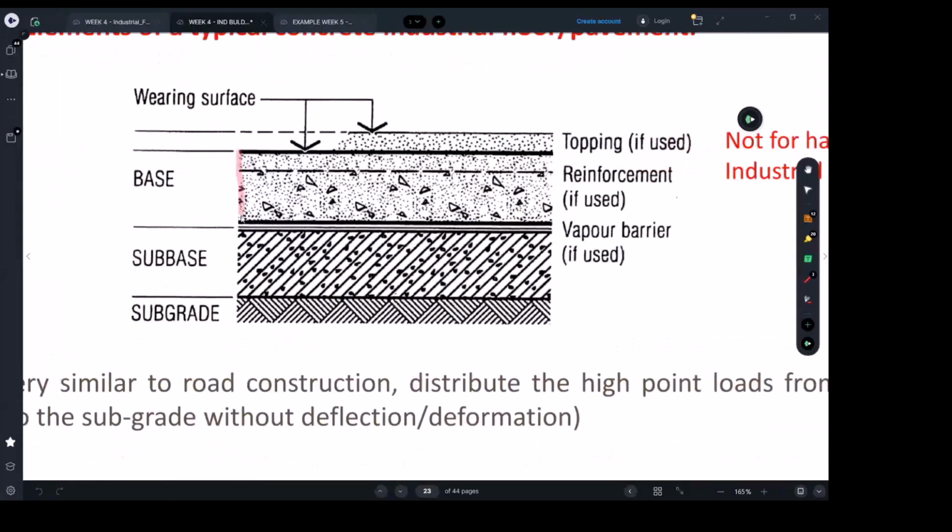The industrial concrete slab is this one. See, this is the top, this is the concrete slab. In this case, you can see it's got one layer of steel at the top, which was enough. This part here is that black sheet, to prevent moisture coming from the soil to the concrete.